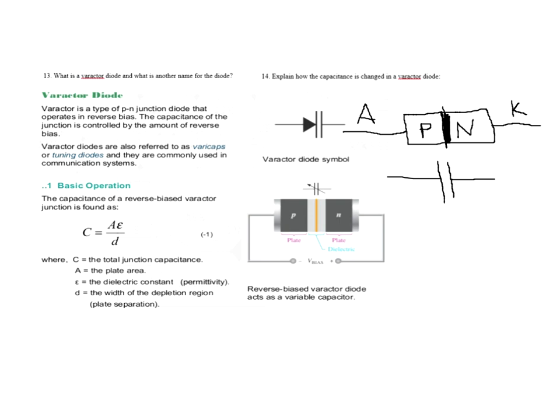With a higher voltage on the cathode, this depletion region gets bigger inside of there. And that makes the plates appear to be further apart. And that's what this whole discussion is about here. Here's what they're telling you. Here's the P material that's acting like a plate of a cap. Here's the N material acting like a plate. And the dielectric is actually the depletion region.